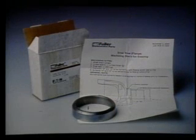A yoke sleeve kit, Fuller part number K1940, is now available to repair a worn or damaged yoke. The kit contains instructions that show how to turn down the yoke and a hardened sleeve which is pressed on the yoke. There are no other acceptable repairs that can be made to the yoke.